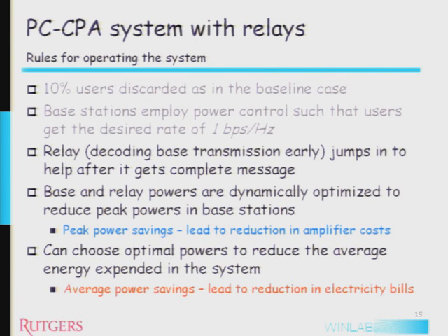Think of it like a multiple antenna system, where there are 3 transmit antennas, one corresponding to the first phase when the source is transmitting alone, and the other 2 corresponding to when the source and the relay are transmitting. At the receiver you only have one receive end. It's like you have two receive antennas, one receiving the first phase and the other receiving the second phase. So it's as if you had three at the transmitter and two at the receiver. I'm using time to recreate a spatial system.